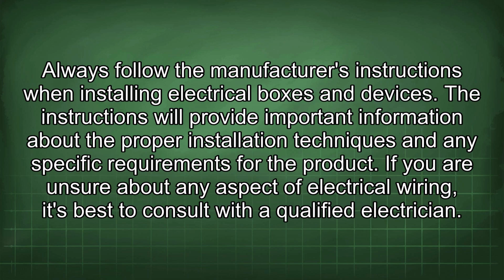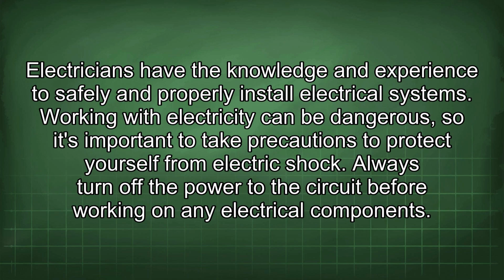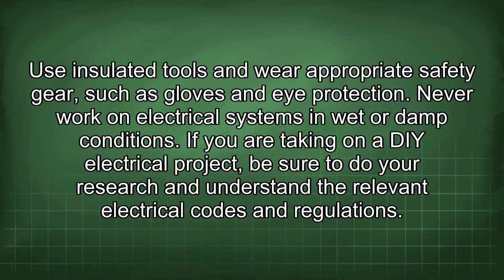If you are unsure about any aspect of electrical wiring, it's best to consult with a qualified electrician. Electricians have the knowledge and experience to safely and properly install electrical systems. Working with electricity can be dangerous, so it's important to take precautions to protect yourself from electric shock. Always turn off the power to the circuit before working on any electrical components. Use insulated tools and wear appropriate safety gear, such as gloves and eye protection. Never work on electrical systems in wet or damp conditions.